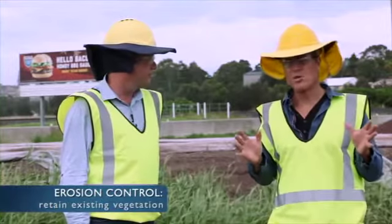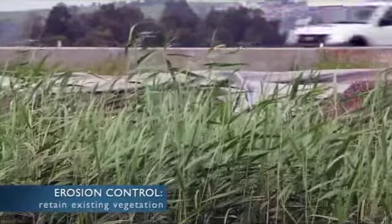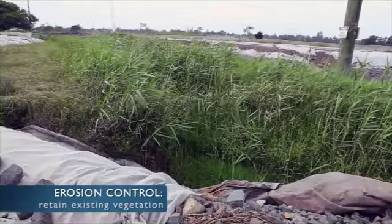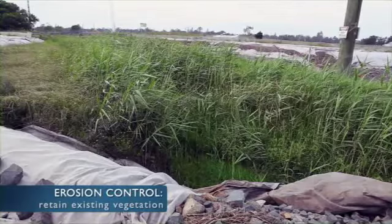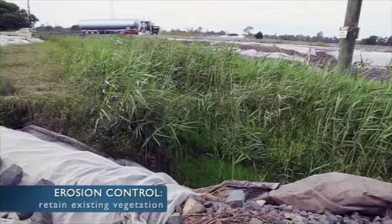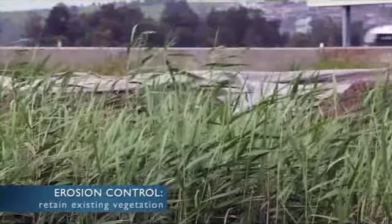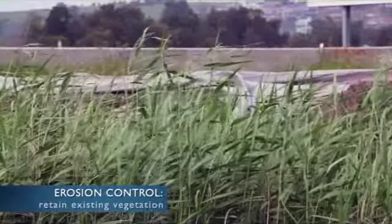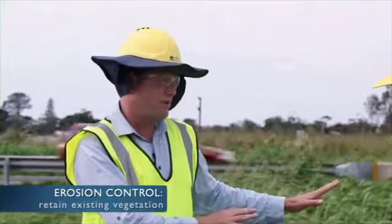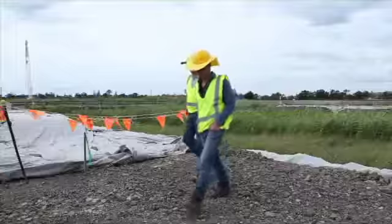Is it fair to say you want to keep the natural vegetation in place as long as you possibly can? Absolutely, Pete. So what we can see behind us is a good example. We're actually constructing a bridge over here. What the bridge will do is concentrate high energy flood events through this channel adjacent to the bridge. So we need to put rock armour protection around that bridge. What the team here are doing is retaining that vegetation for as long as possible. And what they'll do is, on a daily basis, remove vegetation and then put that rock armouring in place, so we're not going to have an erosion risk. Okay, so let's take a closer look at some of those erosion control techniques.